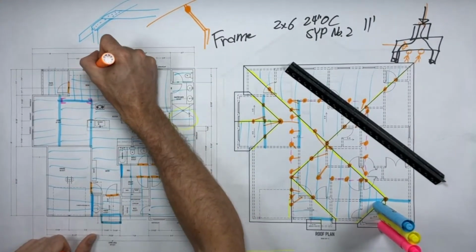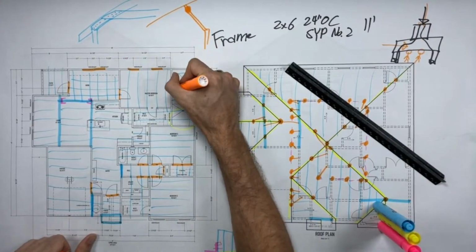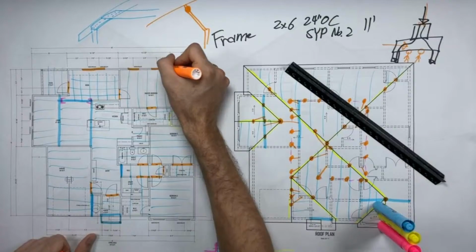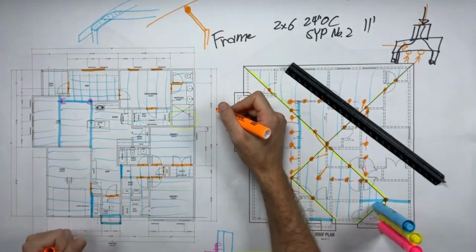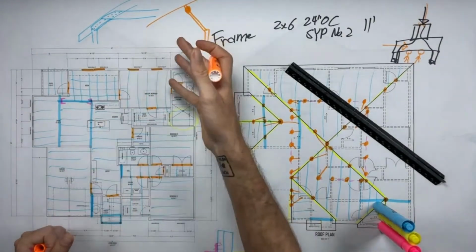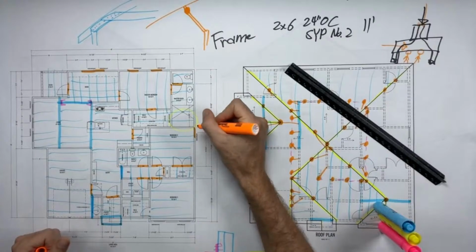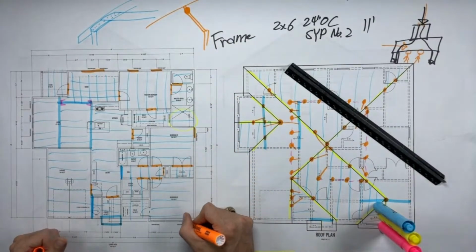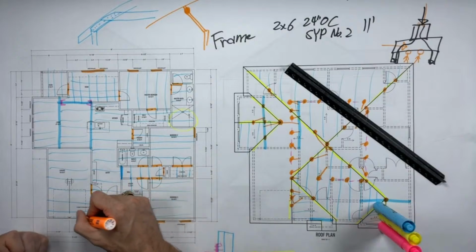Generally, I would define a header as inside a wall assembly, like it's built into the wall. When you raise the wall, you're putting the header in the wall. And generally, I would describe a beam as something that sits on a wall. That's generally the lingo I would use if I was being picky, or just if I wanted to be consistent and describe the same thing to people.